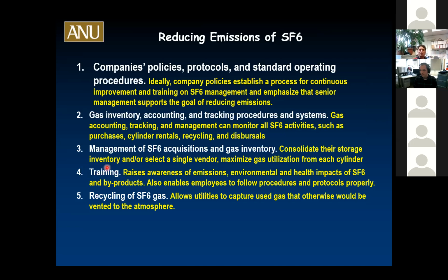Of course, this should include training. It's not only confined space, but also high pressure gas, and raising awareness of emissions and the environmental and health impacts of SF6 and byproducts. Because we should remember that during operation of an accelerator, we also produce some breakdown products, and there could be some toxic components. Always ask ourselves the question: what are the tiny deposits left on the surfaces when we enter the tank? So it's maybe not trivial and should also be important.